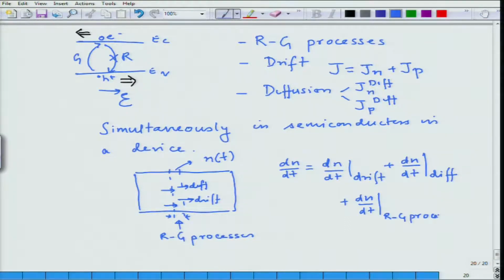and generally when we talk about RG processes, this is also what we are talking about, which are mainly thermal processes. And then we split out another term for generation, which may be due to external sources, which is change in the carrier concentration due to other processes. What are these other processes? As we discussed, the generation can be due to thermal reasons, or the generation can be due to the injection of carriers or due to excitation by a light source.